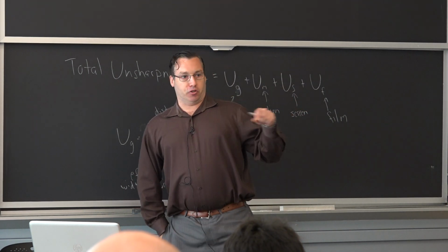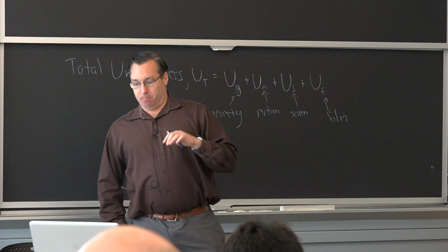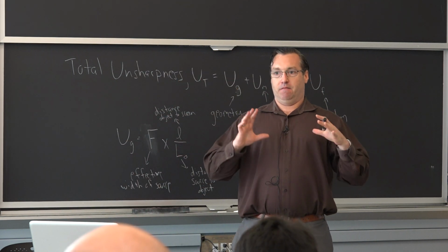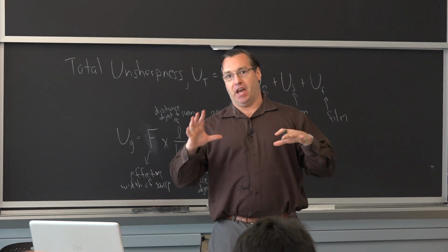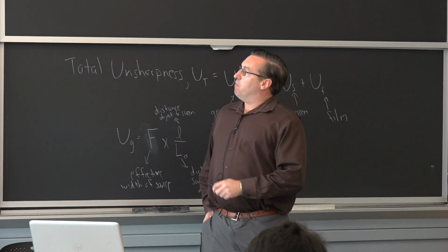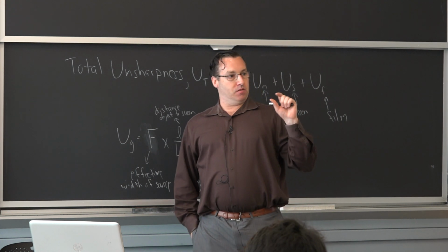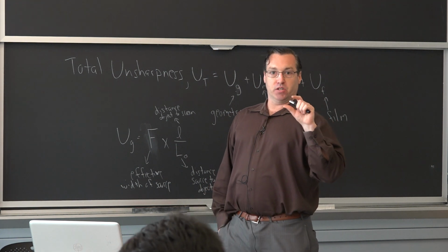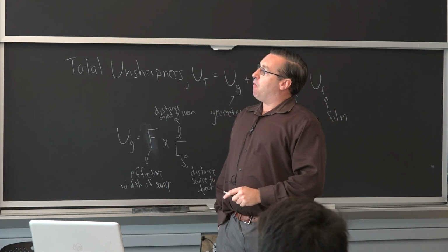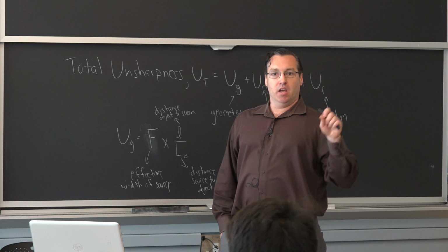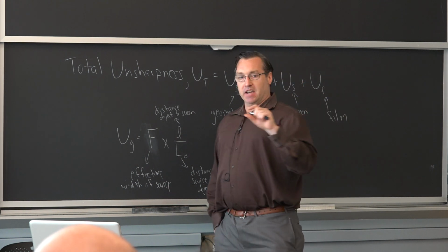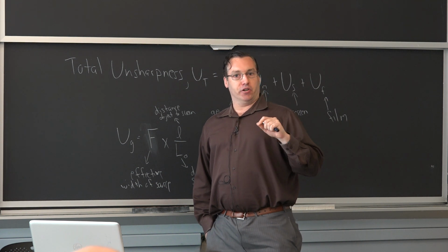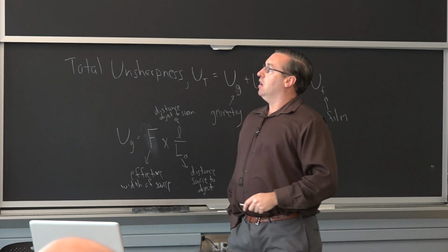One of the things in industrial sites when you're doing radiographic testing on large structures, whether it would be a submarine or a bridge deck or something like that, when you need to get sources higher than X-rays, you'll go to a gamma ray source. I can touch upon it today, but the isotope used for the source varies depending on how much energy you need to interrogate the sample.